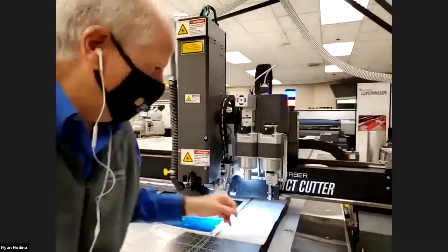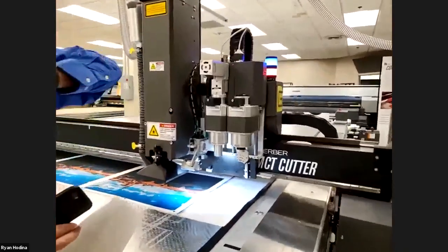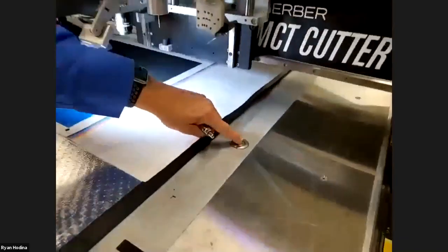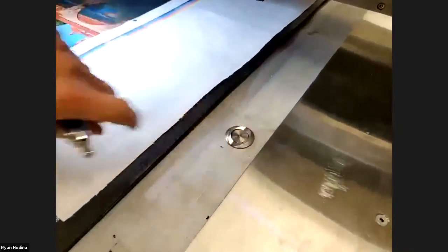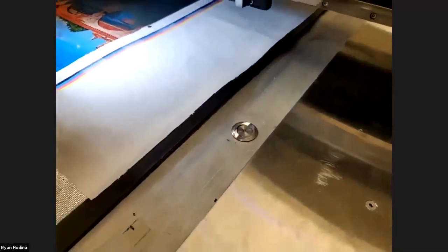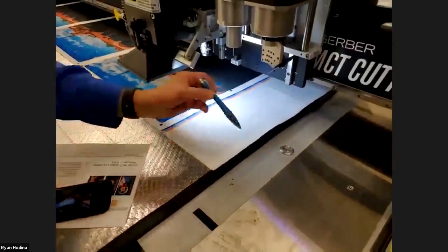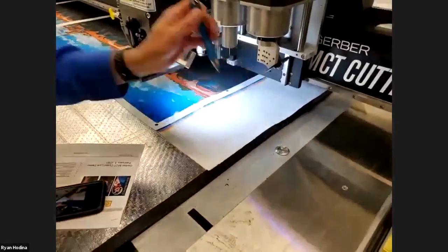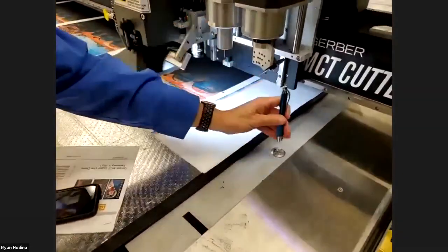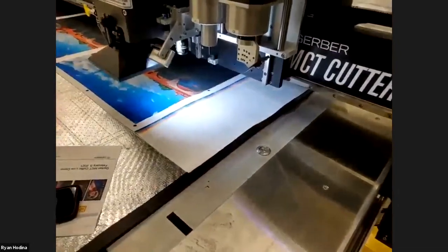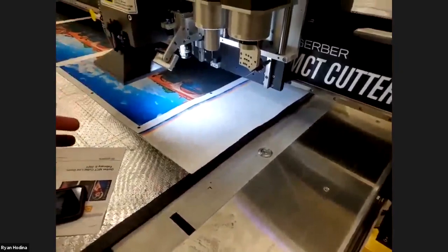While I'm here, I want to point out one other item. It's called an auto touch-off tool. That's what this device is here. This is a sensor. So as you put in a new tool, that's going to take care of how far a router bit or a knife tool might be sticking out of its collet. And that's the purpose of this sensor. So we're going to bring the tool over, take a reading, and we'll know exactly the Z-axis position of the tool.